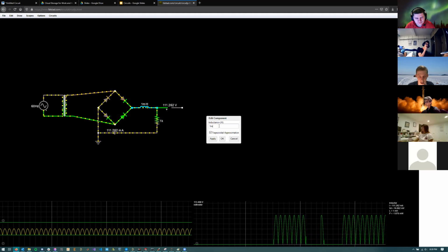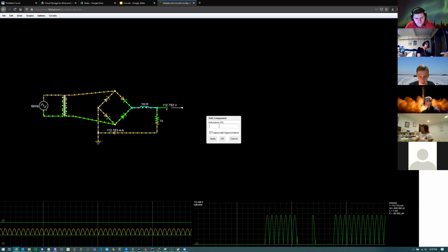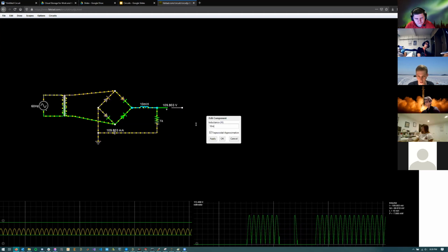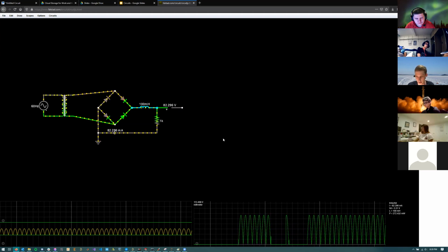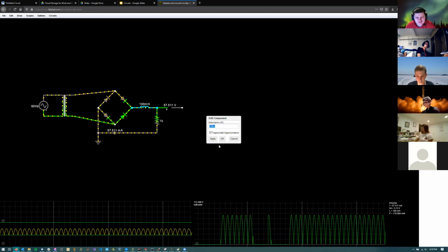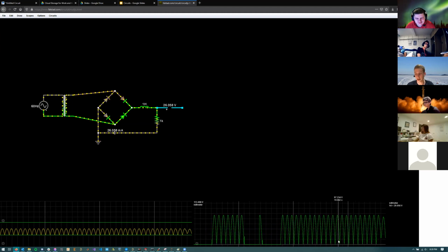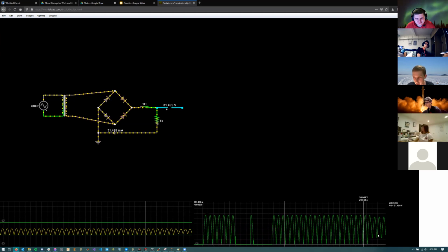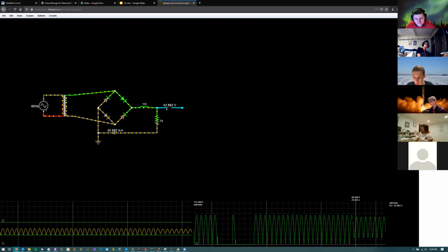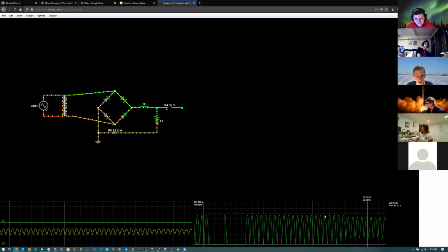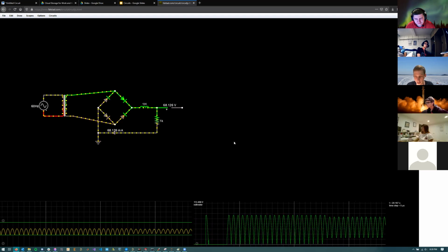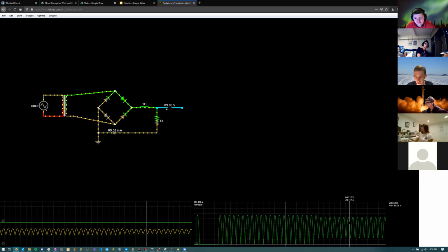However, if we increase the inductance, so we go to, let's see, slowly increase it. Millihenries. No, you've got to go, because it's saturated. Yeah. All right. So you'll see when we actually get the inductor starting to smooth out the output current, our output voltage actually decreases here. And we don't want that. We still want our full power being transmitted, essentially, or our full voltage.